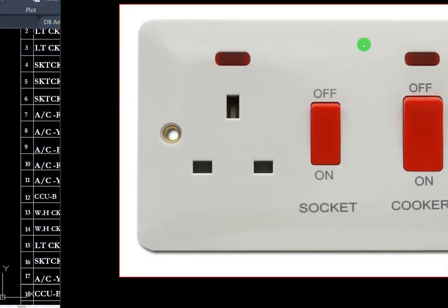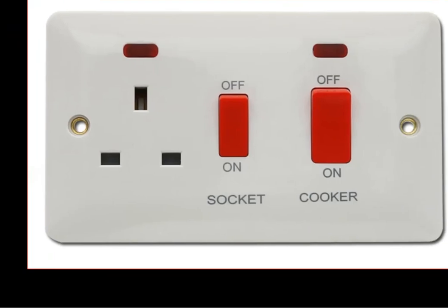Look at the cooker in question. This is the cooker. Now, this is the socket we are referring to. The 10 amps that I want to subtract and add back belong to this. This socket outlet is not for the cooker. This is an auxiliary socket attached to this cooker for other smaller current-using equipment like a blender and a small toaster. You can use it, but this is not the outlet for the cooker. The cooker is not going to be powered through here. The connection is at the back. I will show you later.